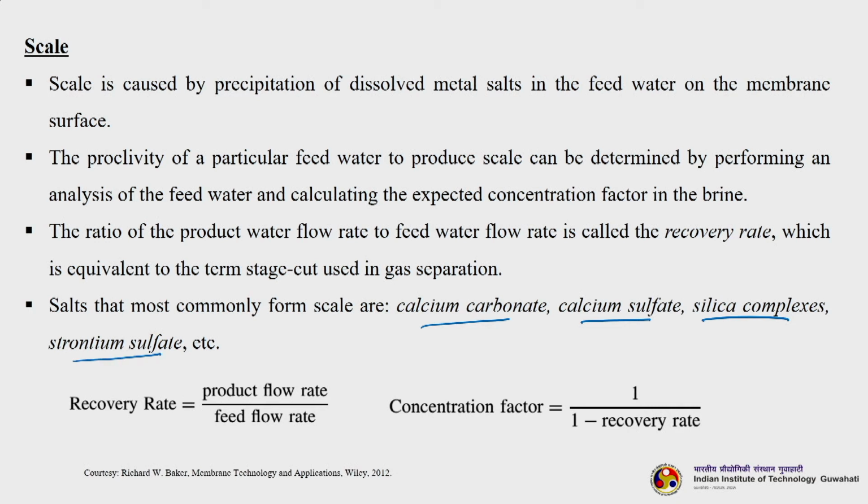Salts that most commonly form are calcium carbonate, calcium sulphate, silica complexes, strontium sulphate, etc. So, your recovery rate is given by product flow rate over feed flow rate, and the concentration factor is 1 over 1 minus recovery rate.